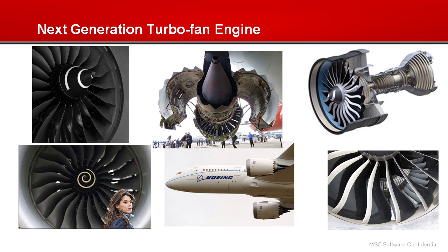In a high bypass turbofan engine like the General Electric GEnx or Rolls-Royce Trent series, 90% of the thrust actually comes from a spinning fan blade in front that draws in massive quantities of air and forces it out in a ring around the engine's center, or what they call the core. The primary innovations are really the fan blades.